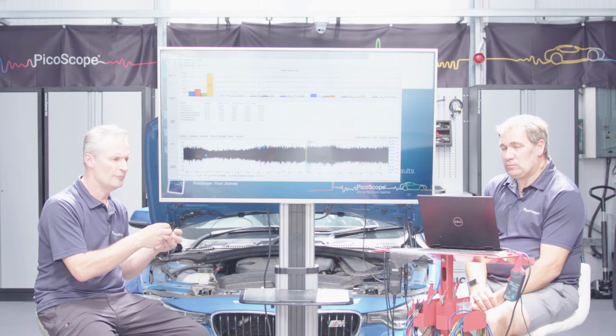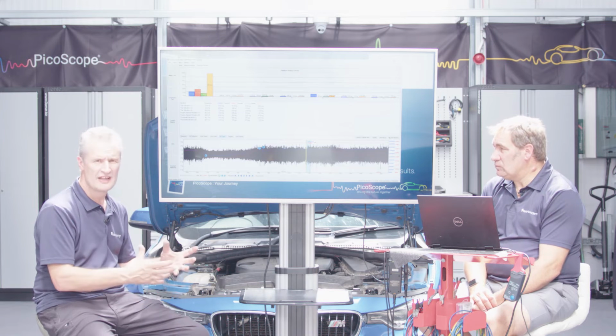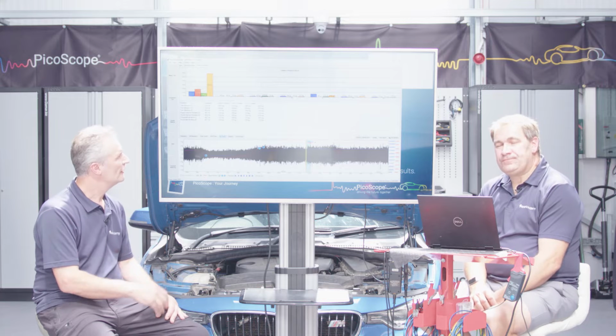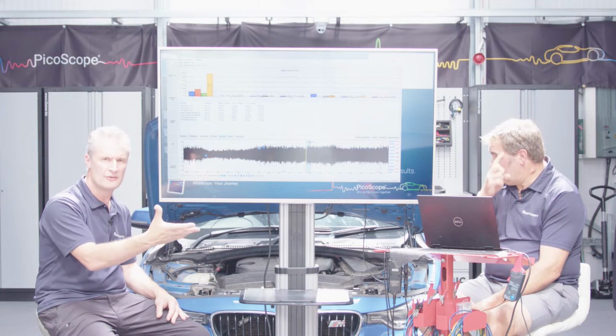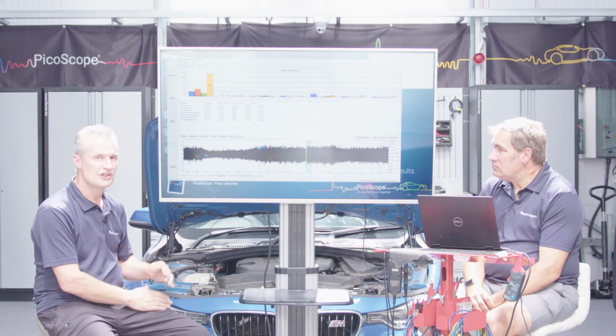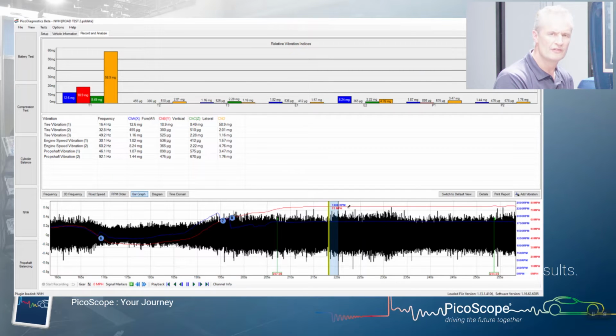So we've now taken an accelerometer outside the cabin, which for all intents and purposes is insulated from vibration. We've now exposed the accelerometer to vibrations outside the vehicle that were originating from the rear left, but through the entire vehicle components, the transfer path that John mentioned earlier, we're picking up the vibration equally at the front. Equally at the front, yes, not to the same level as we were when we were at the epicenter of the vibration. And in that animation you saw there that over the rear left we are now at 58.9 milli-G, far greater amplitude.